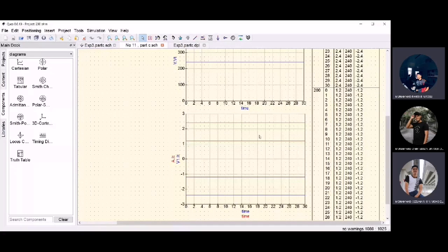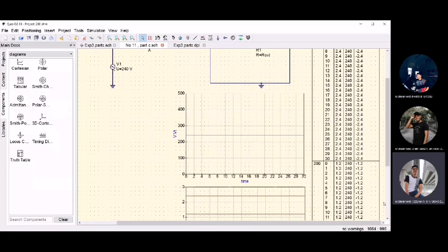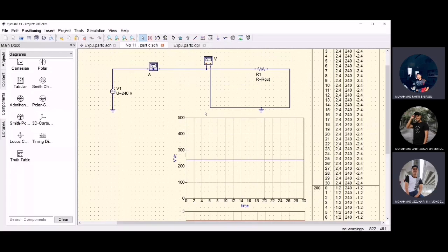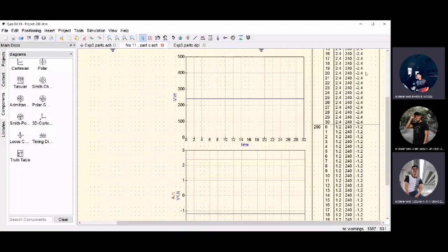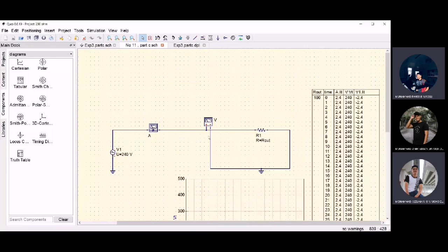With the increase in the value of the resistor R out from 100 ohms to 200 ohms, we get a decrease in the value of current. Using this parameter sweep makes it easier to construct one circuit rather than more than one, and we will get the exact same value. So the parameter sweep helps us save our time and get the precise value.